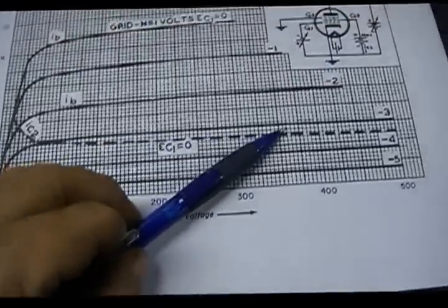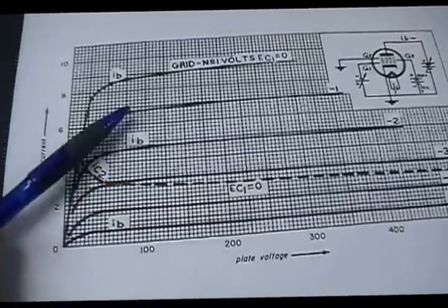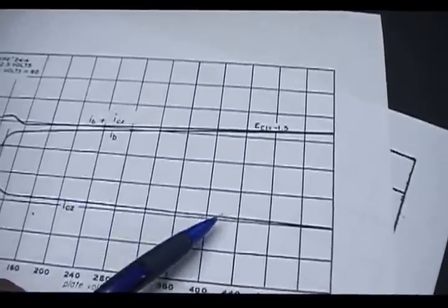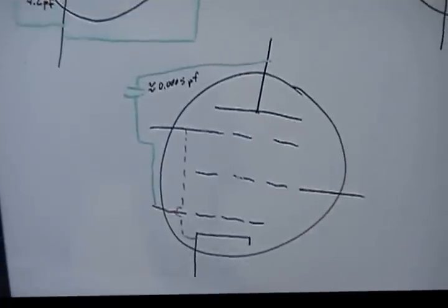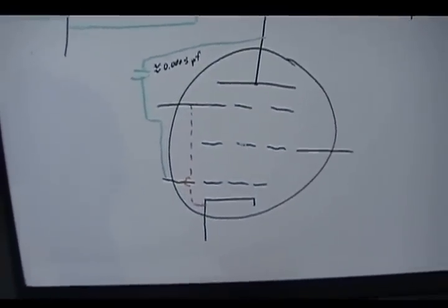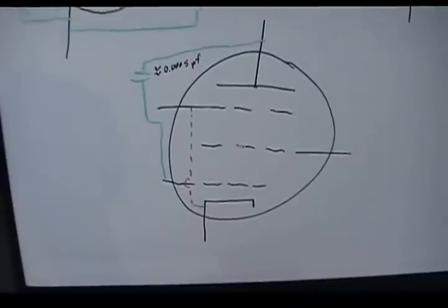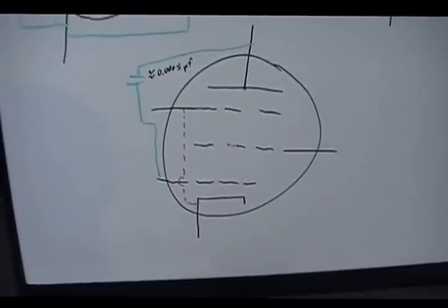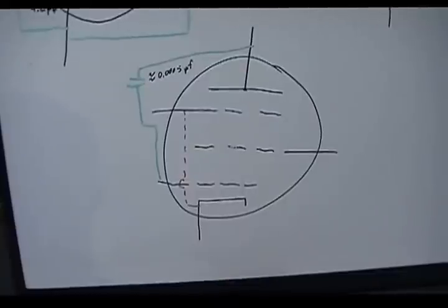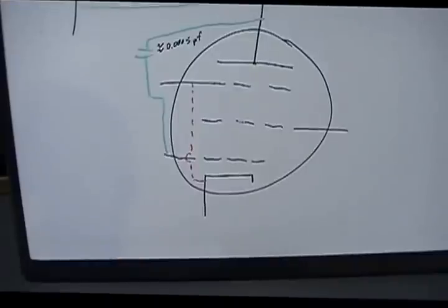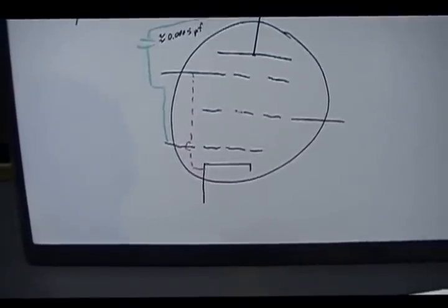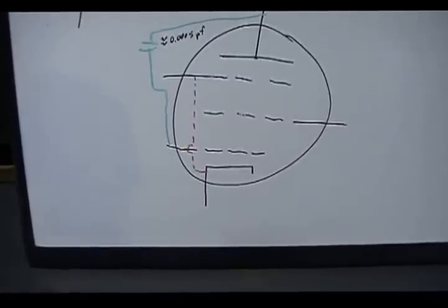Now the nice thing about them is the current is even flatter, much flatter than this current, which does have a little bit of an angle, you can see here. That means mu is probably much higher. Well, it is. A decent average for these, 1600 to 2000 on the mu. So they are quite powerful amplifiers as far as amplification goes, which means that they're more sensitive power amplifiers, and you can get by with a very small signal to an output signal.